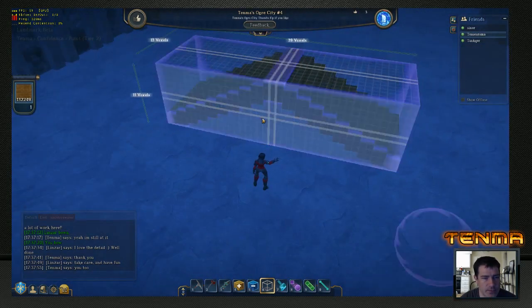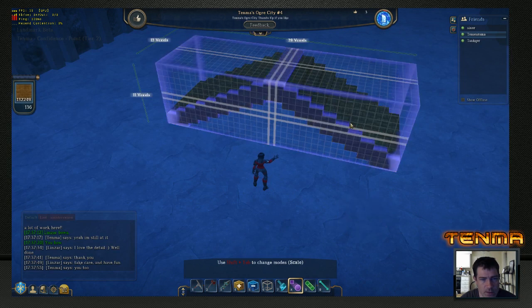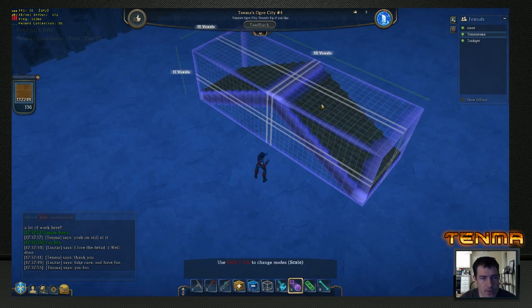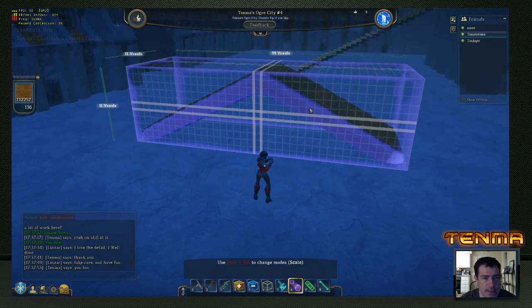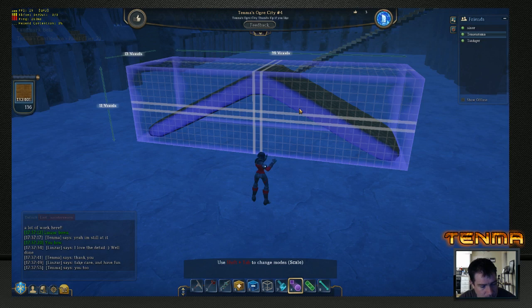I'm going to take my smooth tool, put it on the round one, not the square one, and I'm going to hit this a few times to smooth it out. If you see, I can sit here and hit this thing all day, and it takes forever to burn major holes in it. Let me back this up a little bit because I don't want to take that much off of it.